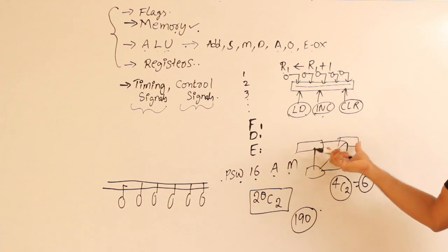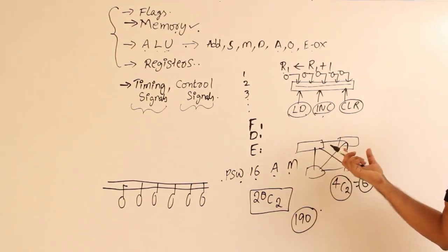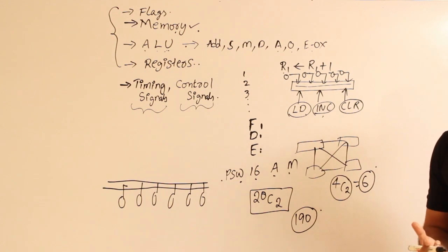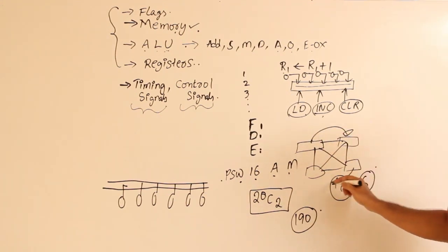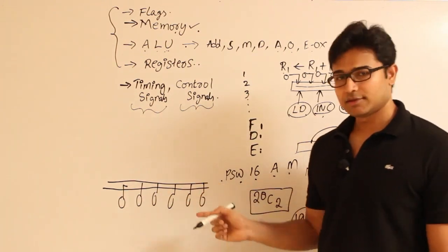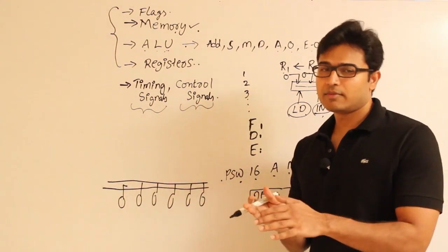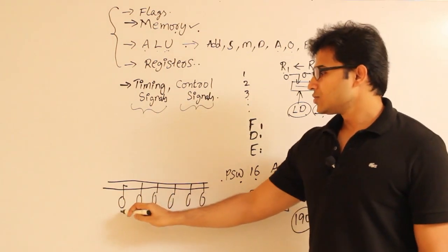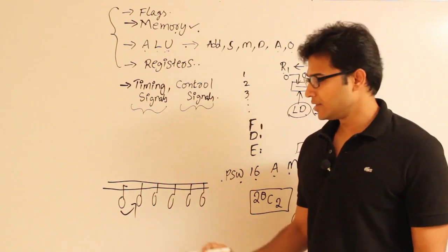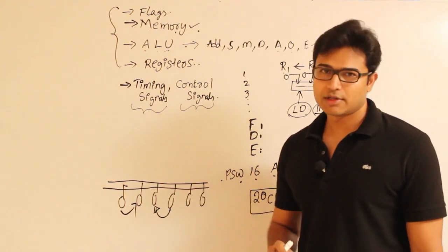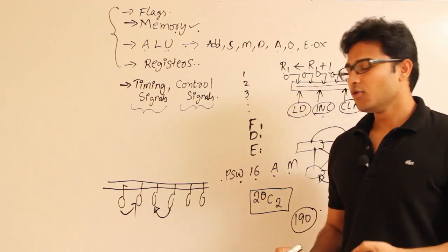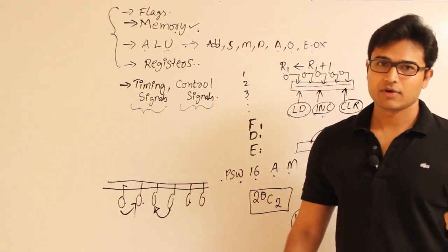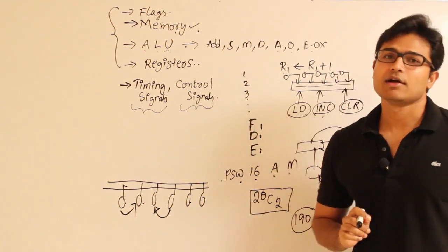See, if you are going to have a point-to-point connection, then you need not worry about who is using the channel. There need not be any monitoring, because if you are transferring data from here to here, at the same time these two can also transfer. But if you are connecting using a bus just to reduce the complexity, the problem is if these two are transferring some bits, at the same time some other 2 parts cannot communicate. Therefore there has to be a leader who controls the information flow between them. For that reason we need someone to produce the control signals.